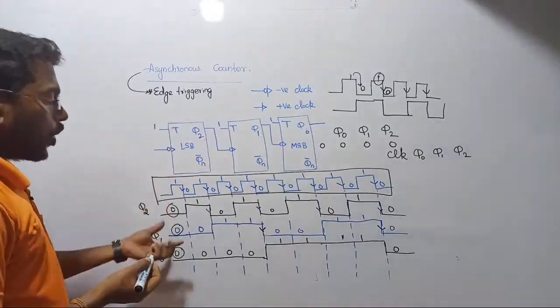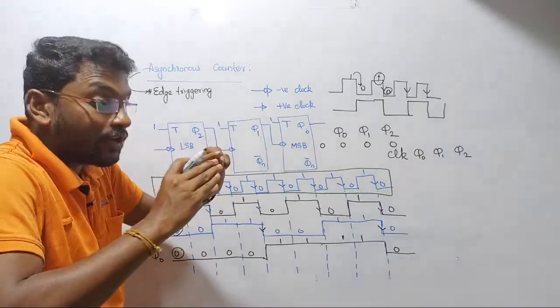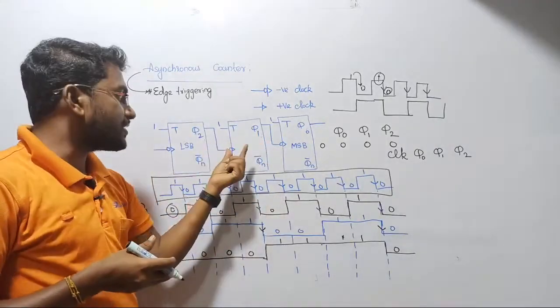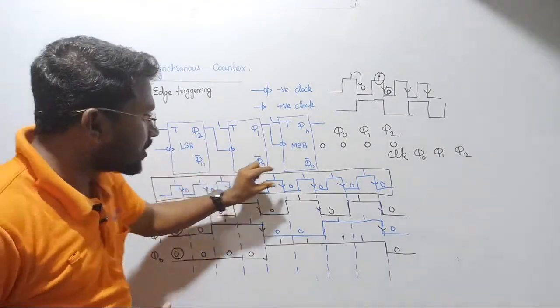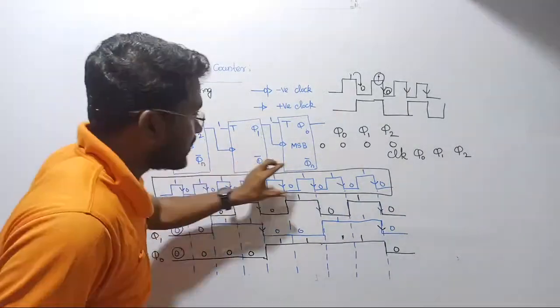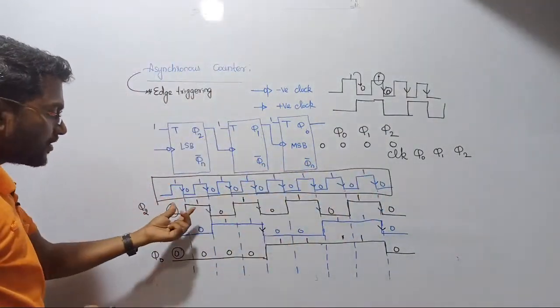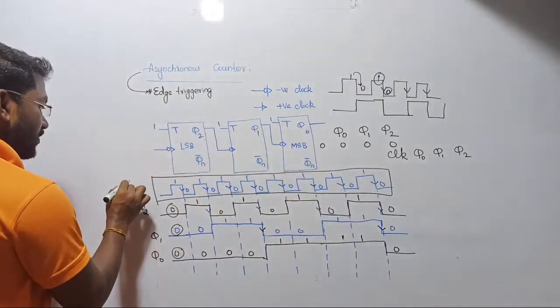The output of the first flip-flop will act as the clock of the second flip-flop. It does not mean that this is the original clock. This is your original clock. After completing the whole operation, you will have to treat this one as the reference clock. You cannot consider these other things as your clocks. This is your reference clock. Clear? He is your hero.